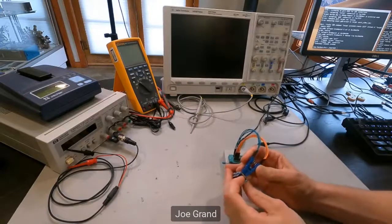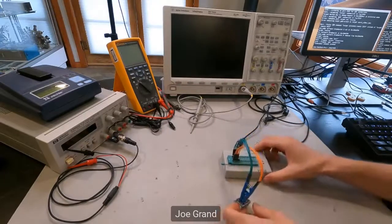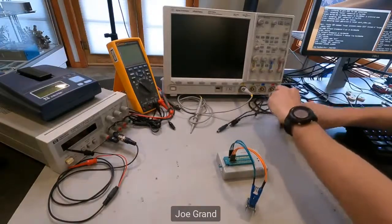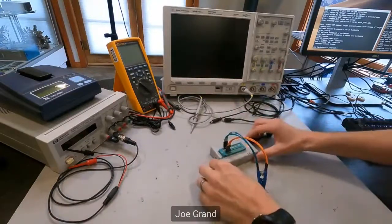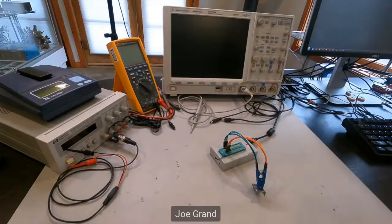So I'm going to clip this onto the individual pins, and we'll see if that works, because the device programmer tool will actually give us an error if there's a pin that's not making a connection, which is good. So I'm going to plug that in. And now I'm going to switch over. Let's see if I get to my right screen. I'm going to screen share my Windows 7 virtual machine that has the software for this particular device programmer on it.